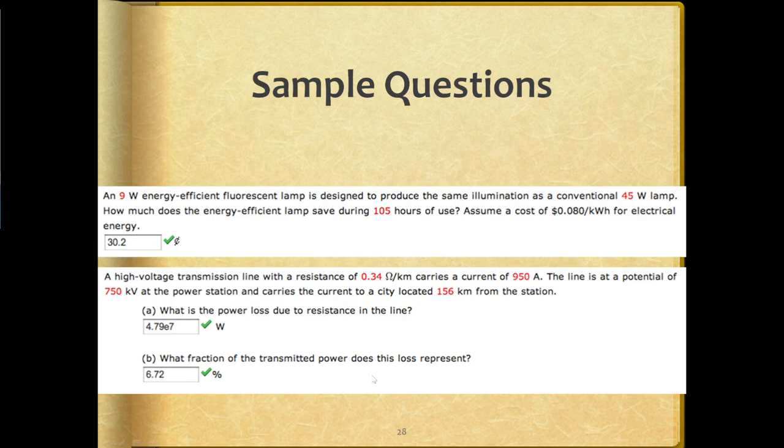Since wires have resistance, and since you can run current through them, one of the formulas for power tells us P equals current squared times R. If you run current through something with a resistance, it eats up electrical power. The wires in a machine, even if their resistance is incredibly small, the fact that they have resistance means they take up some of the machine's power. And this is one reason why the wires eventually heat up and eventually need to be cooled off before they melt or before the machine breaks.